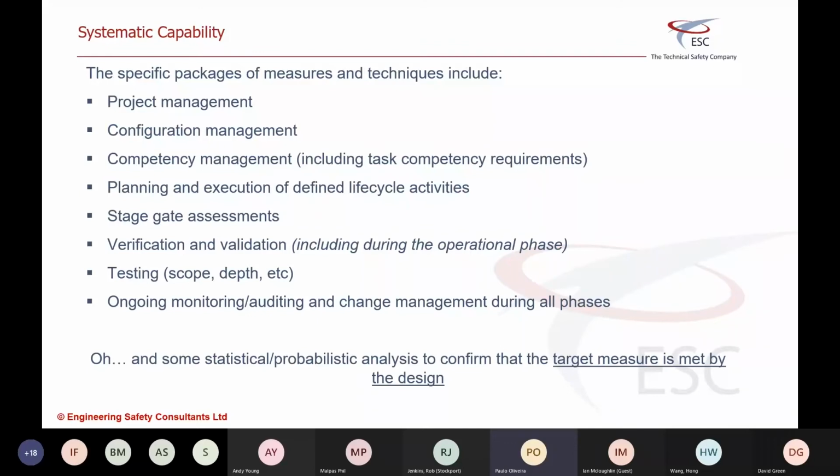Change management should happen at each stage of 61511. A change on a design, for whatever reason, should be revalidated against the safety requirement specification. The same for installation and commissioning, and the same during operations and maintenance. And there's some statistical probabilistic analysis that you can do also to say there's a target failure measure and my design meets it, which is your PFD.